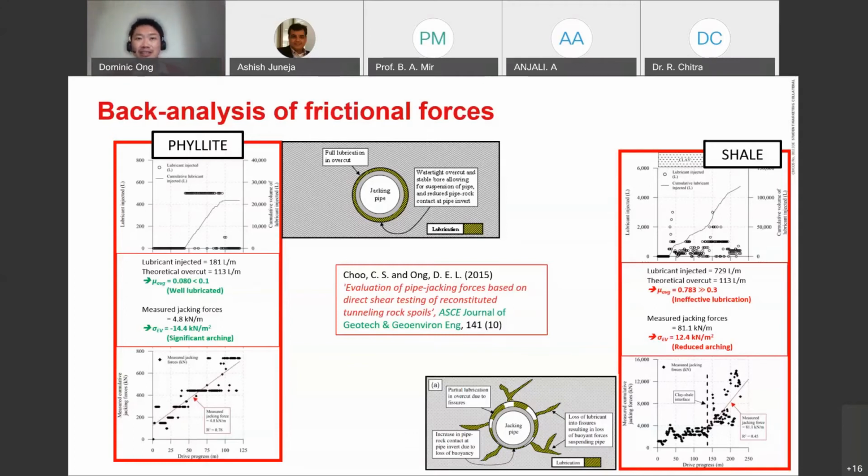And I've got a PhD student, student number 2, Frederick, who has just completed his PhD, where he used pressure meter to interpret rock mass. How we do it is that we couple together, more like a coupled analysis with finite element, so that we continue to develop the yield stress where the physical pressure meter could not achieve, and we use finite element to model to failure. So from there, we'll be able to obtain the equivalent c' and phi' again.